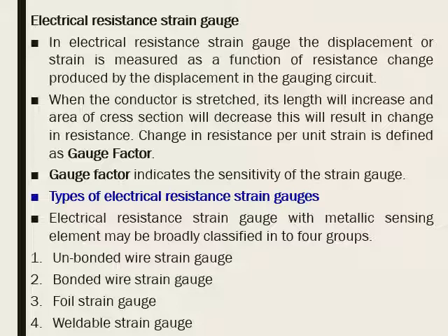For example, capacitive strain gauges are very sensitive to vibrations, and it is very difficult to fix them to the workpiece to be tested, and it may be quite impossible to test a piece whose configuration is complicated. Inductive strain gauges have some disadvantages, and besides, they have much greater weight and size.